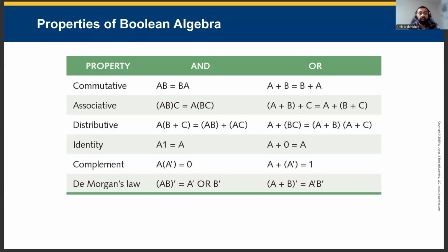Properties of Boolean algebra. Here are some core Boolean properties you'll use constantly. Identity and null laws, idempotent and involution properties, complement, commutative and associative laws, distributive laws, De Morgan's laws, and absorption. Mastering these lets you shrink a design without changing its behavior, often turning a complex-looking schematic into something elegant and efficient.